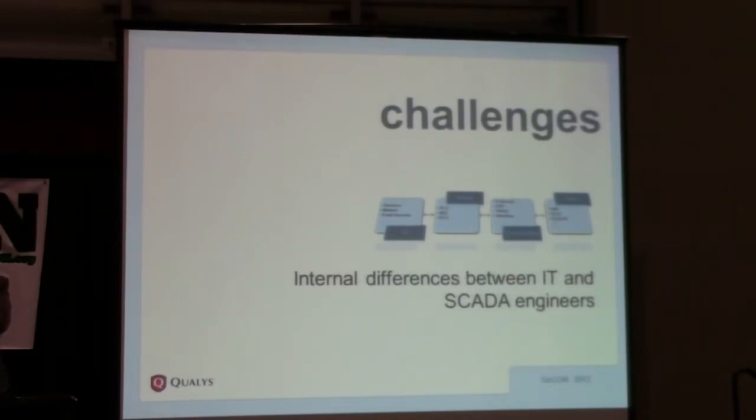In more than one case, we have seen internal differences between the people trying to secure the SCADA system versus the people who own that SCADA system or are responsible to keep it up and running. In a lot of instances, what I have seen is someone trying to secure that system one day runs a blind port scan, or a scan using some tools, on the SCADA network, which causes some of the SCADA PLCs to go down.